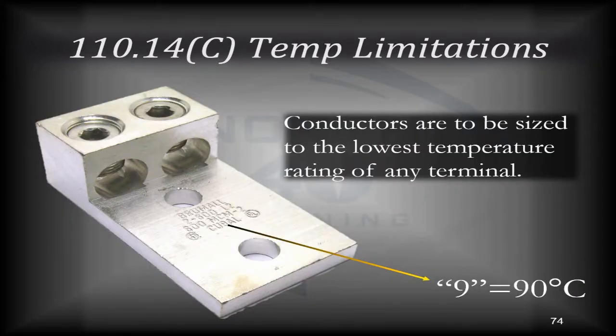110.14(C) talks about temperature limitations. Conductors are to be sized to the lowest temperature rating of any terminal. Notice we've got the 9 on there, pretty much dead center in the screen, and that 9 is indicating 90 degrees Celsius.